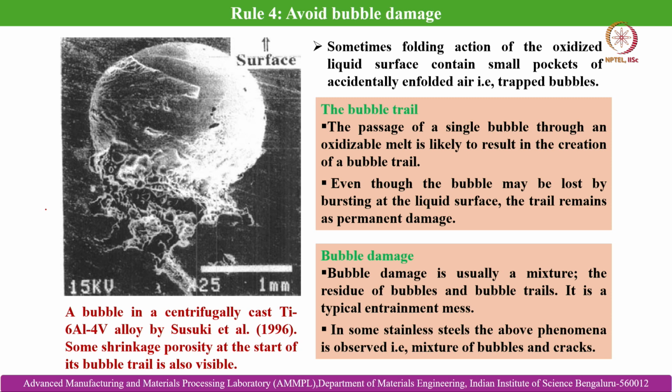There is also a chance of hydrogen absorption if we are talking about liquid melt of aluminum alloys or light metals. Those can cause bubbles to be entrapped within the solidified object,